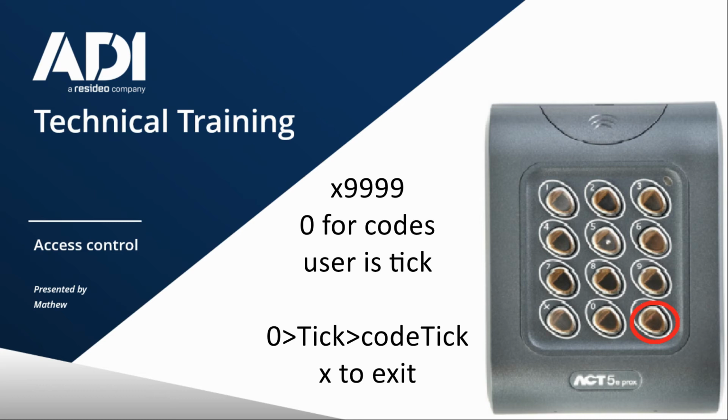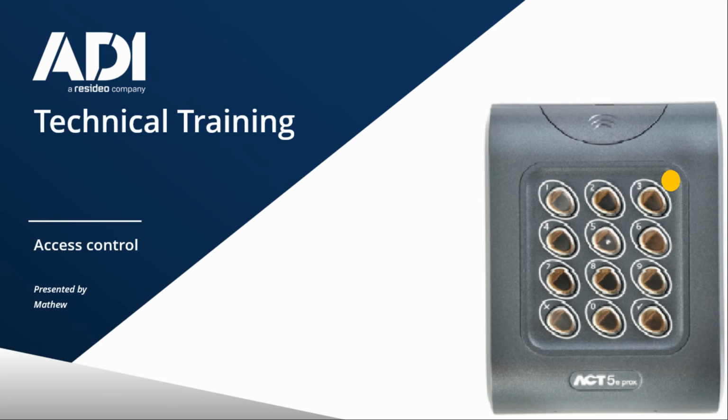You get the reassurance tone. LED is flashing orange to say it's ready for new programming. Press tick, now X. So now the keypad's back in standby mode. So let's just double check that all is good. So X, and then my new code, which is 8 4 times. And there we go, it's done.